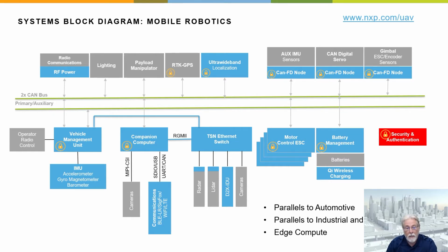And the key thing is that we focus around having a CAN bus. We think that the idea of connecting with a CAN bus really is robust. It can be redundant, and it also leads towards what could be considered a distributed architecture where processing can take place at different places and then a shared data distribution system communicating those results between different modules.